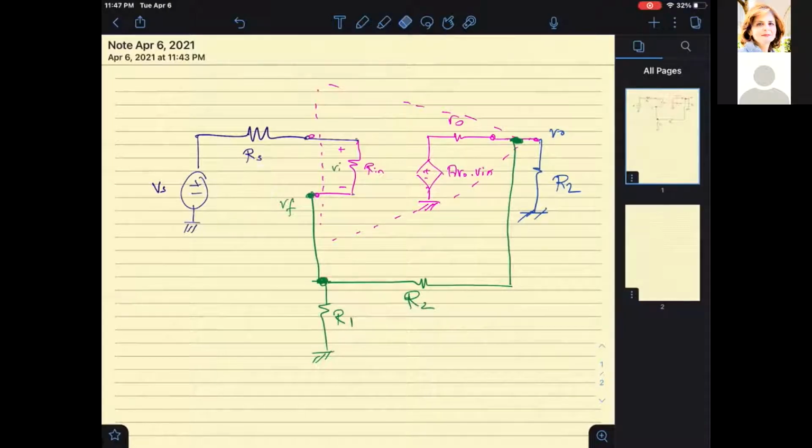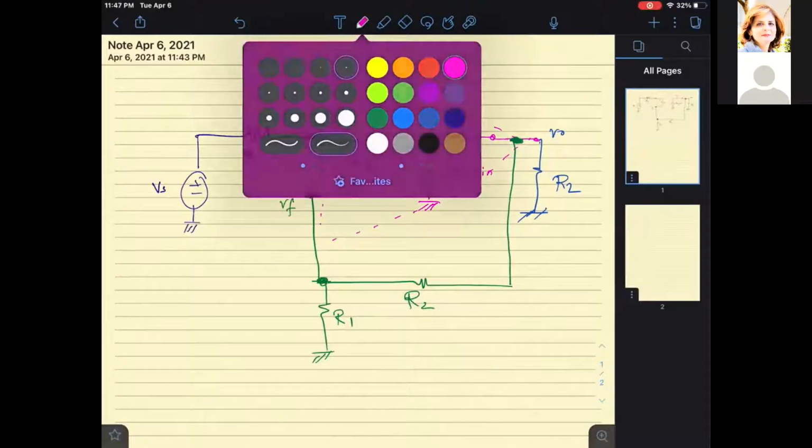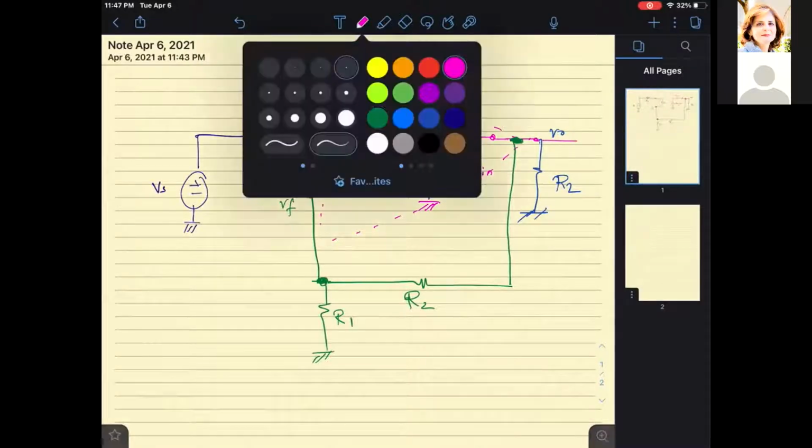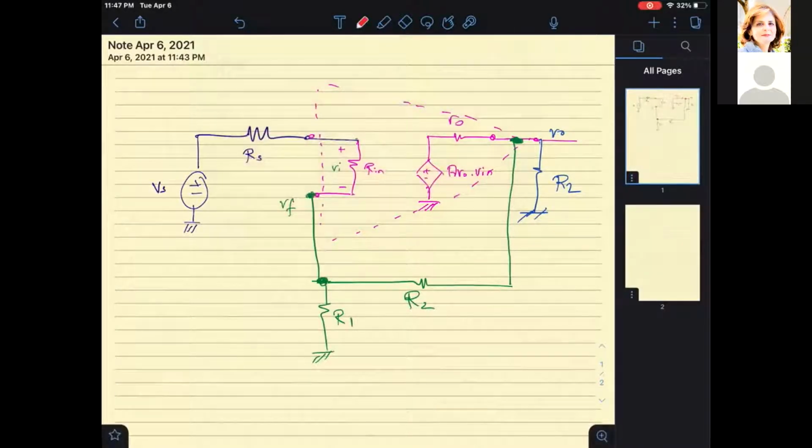Okay, now we typically don't study this circuit as one block, we break it. Let us look at what we have here. Including RL, I will have ROF. Beyond RL, I will have the resistor R out, such that ROF is equal to RL parallel R out.